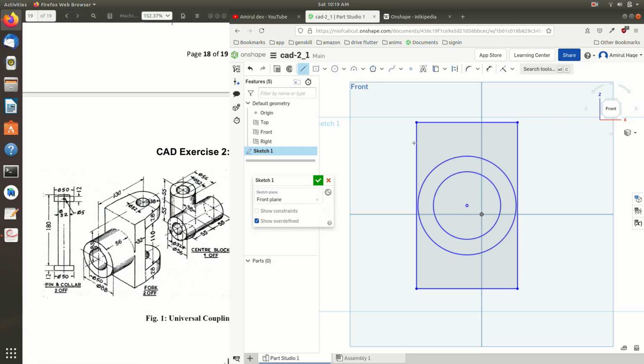For that, let me draw a line, and get rid of this tool by clicking the escape button. And another line. When we place it on this line itself, the line is highlighted, and the automatic constraint, called coincident or intersection, is displayed. Click here, and it can be in any direction, but when we keep it horizontal, the automatic parallel constraint is shown. Just expand it and click on the other side, so it's defined on all three sides.